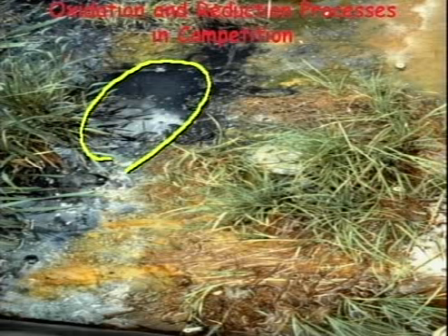And this is what it looks like in the real world. The orange stain is iron hydroxide that formed in the upper inch or so of this cell, and the black material, right in here, was dredged up from below the aerobic zone in the oxygen-depleted anaerobic zone. The plants in this situation increase the oxygen concentration in the upper zone of the cell, which increases the aerobic conditions suitable for iron precipitation. We talked a lot about that earlier.